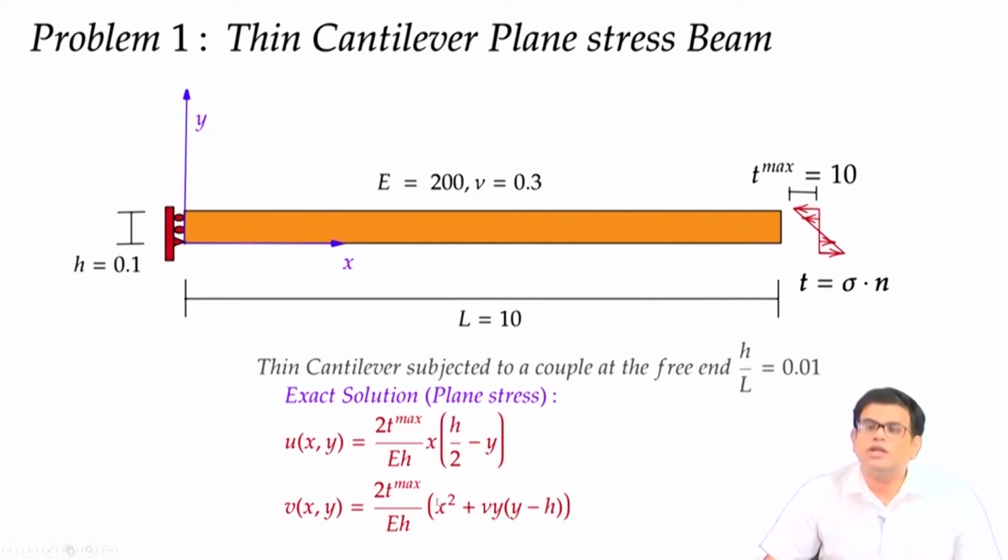This exact solution comes from the 2D elasticity governing equation, del dot sigma equals 0 without body force, with the boundary conditions. At the point x equals 0, 0 it is fixed, and at the other points movement is restricted along the x direction.